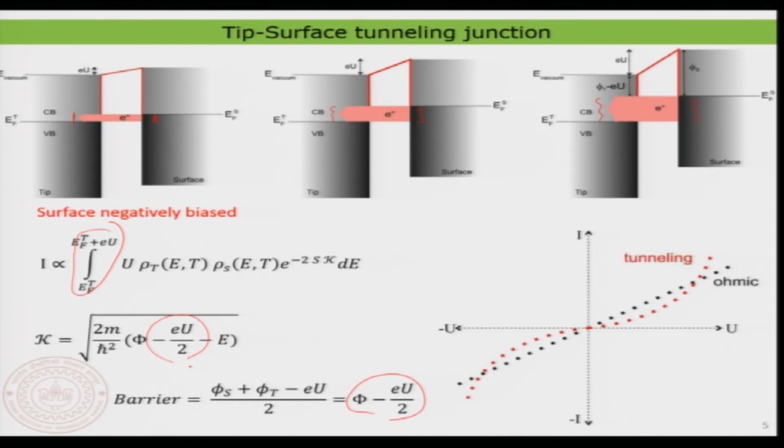So, now we can also make a comparison. You clearly see that the ohmic contact type goes as a linear function with respect to the voltage, as you see here, and the tunneling one has an interesting shape like this. That is the interesting part about it. This is what it generally looks like when you take two metals having similar work function and assuming a somewhat constant density of states near the Fermi level.